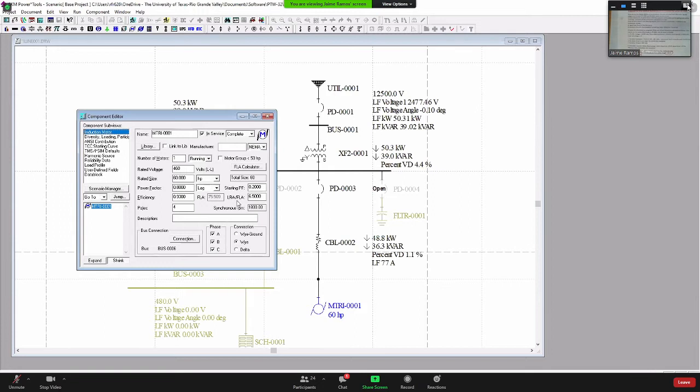Okay, so locked rotor is the denomination that is given to the condition of the motor when it starts. So when it starts, the motor is not moving as if it were locked. However, it will draw a current which is 6.5 times higher than the full load current.